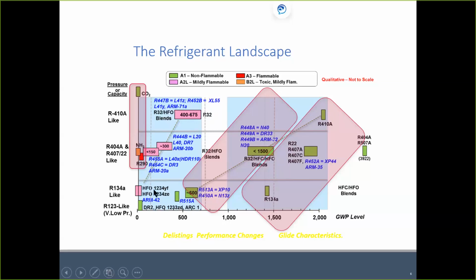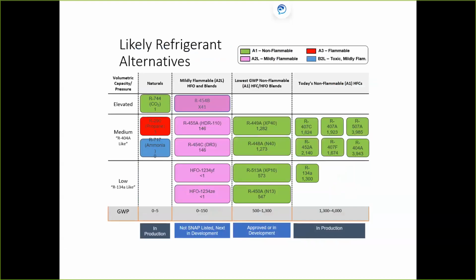And let's take this example here. I try to take the fear factor out of these refrigerants when I'm teaching younger students because it all looks foreign to them, obviously. They only have an 8-hour window to see this stuff that we teach a lot of times. So the other thing I point out is 1234YF. If you know anything about automobiles, and even if you don't, this is a refrigerant we've been using for quite a few years now, 5, 6, 7 years. It replaced 134A. 1234YF, you're going to see a lot in the new refrigerants coming down the line. It's going to be a part of many, many blends down the line is what I'm seeing and what I'm hearing already, okay?